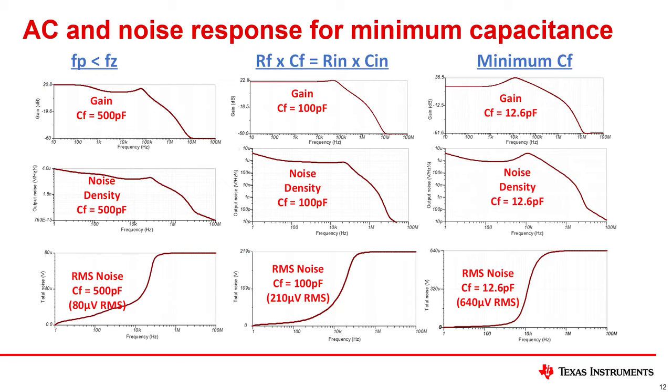Note that this case has some gain peaking because of the capacitive loading we discussed in the previous slide. Nevertheless, setting the pole frequency to a low value limits the bandwidth and consequently reduces the noise. In general, you will see similar noise and bandwidth results for other circuit designs when adjusting the feedback level.